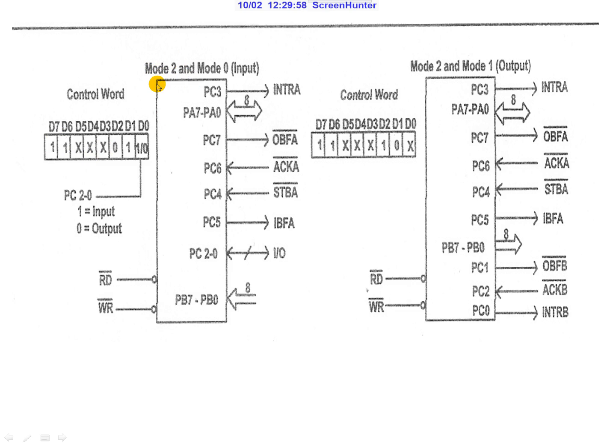D7 is going to be 1 because here we are going to use this as an input output mode, either mode 0 or mode 2. So this pin is going to be 1. D5 and D6 are going to be used for mode 2, and D5 is going to notify either a 0 or 1. Whatever may be written, we can use this particular mode 0 as an input.